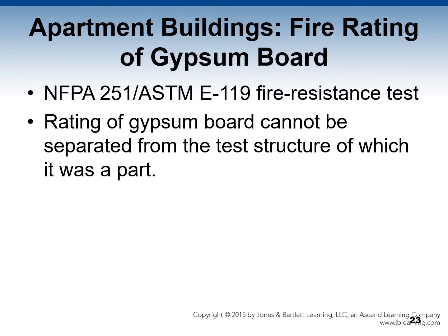The fire rating of gypsum board, in terms of the National Fire Protection Association Standard 251 and the American Society of Testing Materials ASTM Standard E-119, these fire-resistant tests grant a 1 hour or greater rating between these two standards.